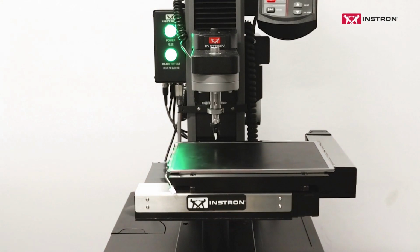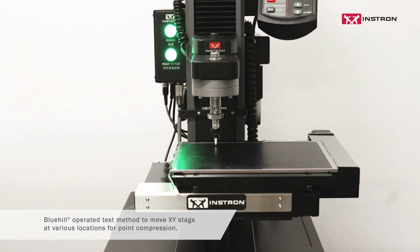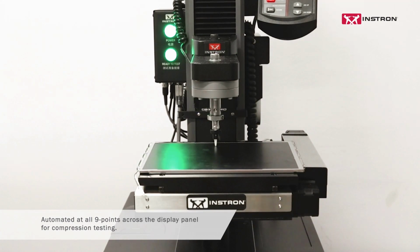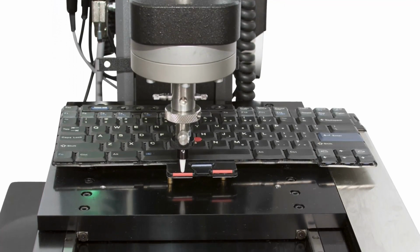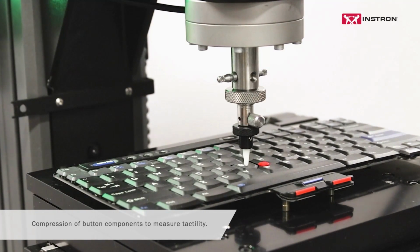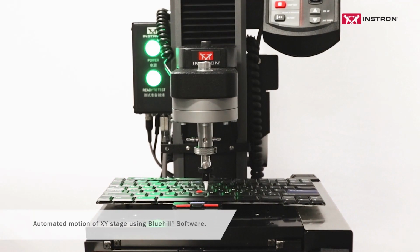I'm going to begin with some videos to show you some XY stage applications. XY stages are commonly used to test electronics, such as screens and keyboards. A compressive load is being applied at 9 points around the screen to simulate loads it may experience in use. Keyboard keys and trackpads are tested to measure tactility. This helps suppliers achieve the feel that consumers want in their products. After each test is complete, the stage automatically moves to the next key.